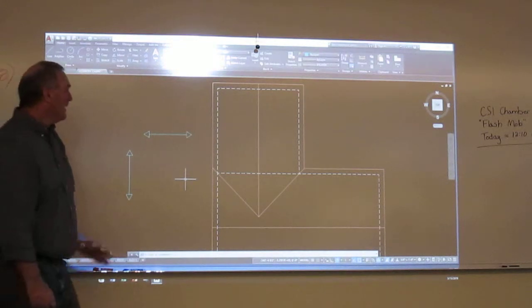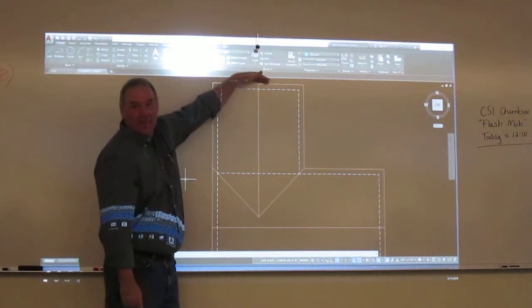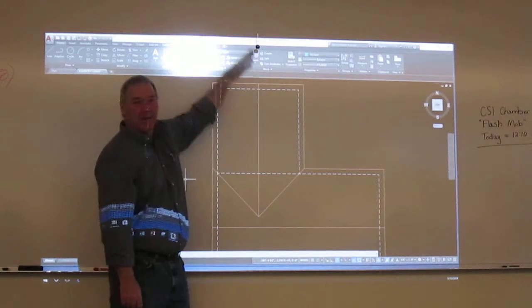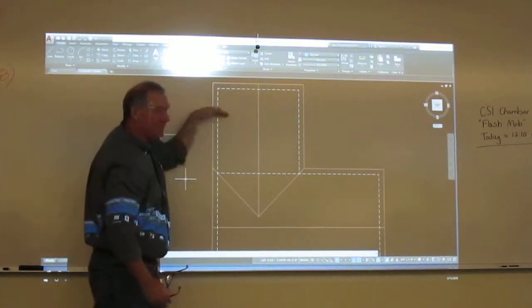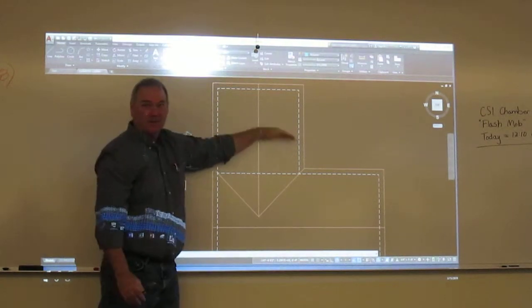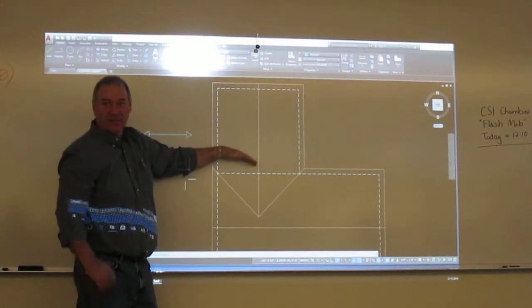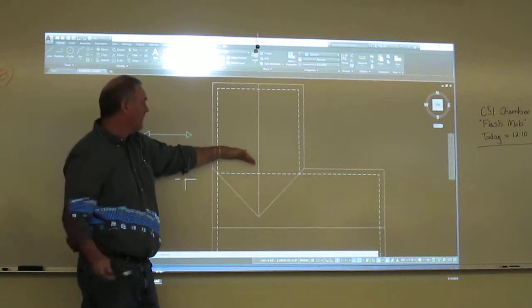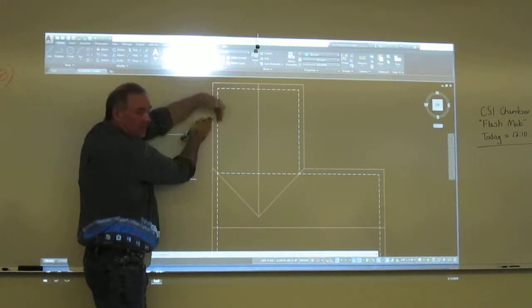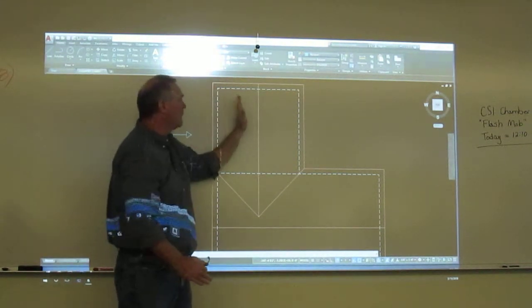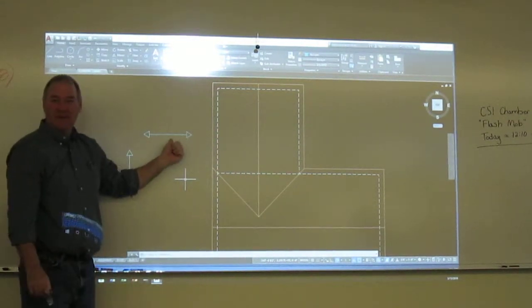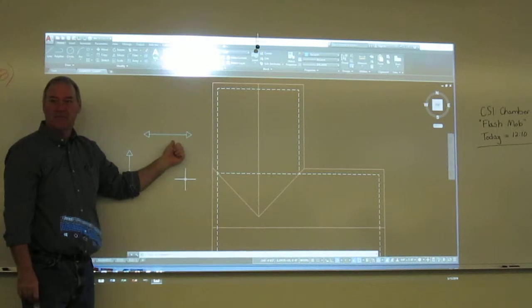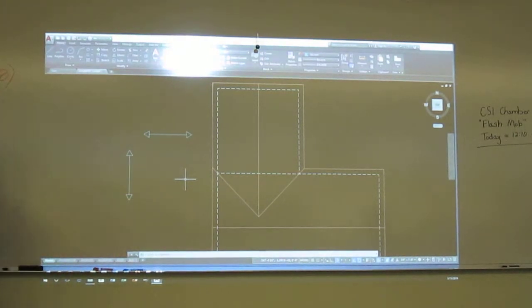Okay, now, if your gable end is here, this is the big wall coming up, and my pitches are running this way, that means my trusses are going to go this way, right here. And they're going to be set every 24 inches. Now, some of you have changed that. Lisa, yours is the first one that comes to mind. Your gable end is here, so your trusses have to run this way. You want to set your framing node in the same direction your trusses are going. So in this case for mine, it's here.